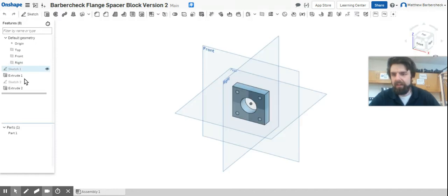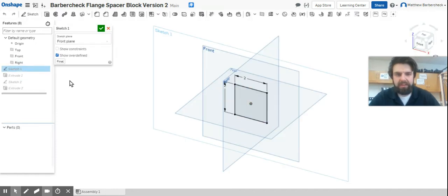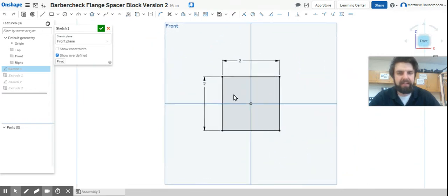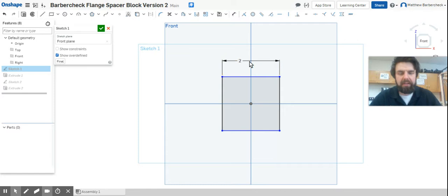All right. So let's just go into our sketch 1 here. The first thing I'm going to do is, I've already got, here I am talking about how this one's going to be much better, but I just realized the mistake I made. Let's set an equal constraint between this and this. Now, if you don't know if your part's always going to be a square, then you might not do this. But this is just an example of one dimension. See how it turned black? Because it knows it has to be equal to that.